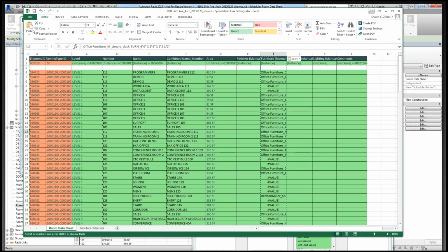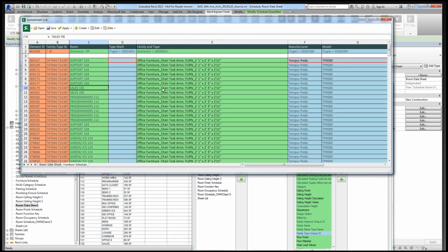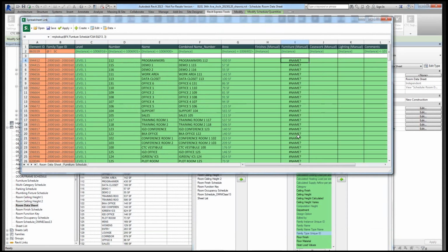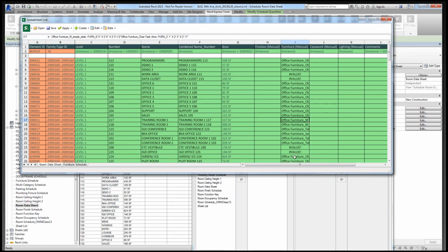All right. Now that that's done, I can reapply this back inside of Revit. I did warn you, it's kind of a clunky workflow, but it's much faster for me to get this information that way than it is for me to manually type it out on each of these rows. So I'm going to reopen that workbook. Specifically, this time it's going to be an XLSX file, the one that doesn't have that math in it. And I believe it's this guy right here. And so it's now got my values inside of there. It's all been calculated out, so I can see what the different values are.